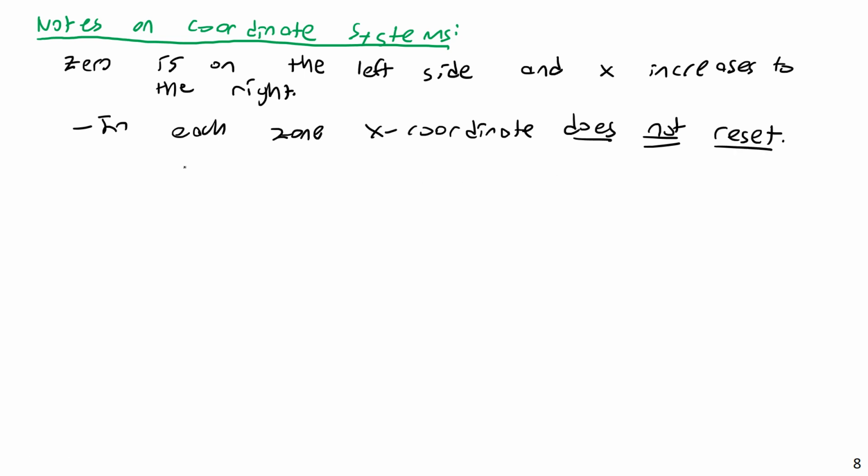So what do I mean by this? Well, let's say you have a beam like this. Maybe a nice simply supported beam. A point load here or something. And maybe we have another one here or something like this. And let's say this was 4 feet, 4 feet, and 4 feet. It's very tempting when doing a free body diagram or doing a cut here, for example, to try to redefine your x coordinate as this point here.